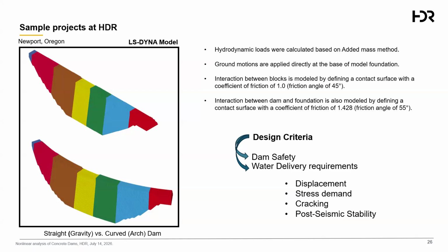This is one of those scenarios that in this course, obviously, we don't consider. We assume everything is fully bonded to simplify the analysis, but in practice, in scenarios like this, you may end up defining complex contacts, and you may spend, I guess, days on understanding what's the more realistic contact to be defined for that particular analysis.